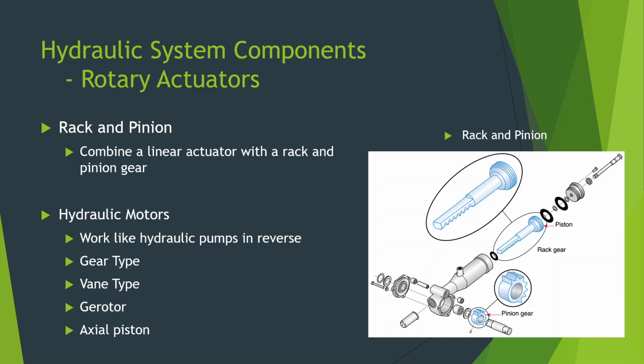Now the other side of this, below here I have hydraulic motors, and we've seen a hydraulic motor in action already when we were talking about power transfer units earlier on. Back when we did pumps, I talked about how a power transfer unit is essentially a combination of a hydraulic motor and a hydraulic pump. And most hydraulic motors that we're going to see on transport aircraft work like a pump in reverse. So they are piston based. They look very similar to a piston pump, but instead of mechanically rotating the input shaft, and that creates pressure, the pressure pushing on the pistons is going to cause it to rotate.